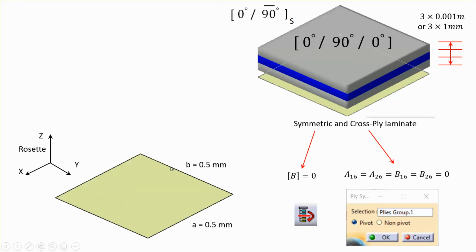Now, the geometry is taken to be square, as I said, 0.5 by 0.5, but we don't gain anything by doing that. It can be a rectangle, and the problem is analytically done for rectangular plates. In that case, there's an aspect ratio parameter that pops up in the theoretical formula that for us is 1. Otherwise, it's whatever the ratio a over b is.